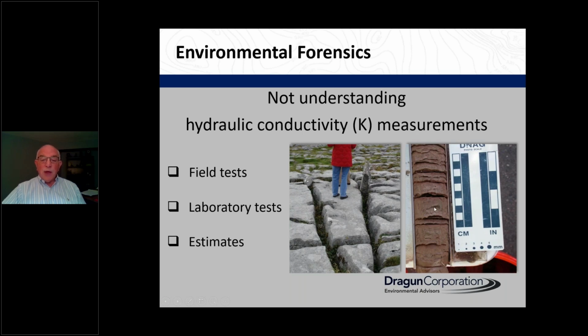And if you were to do a laboratory test like grain size distribution, you would lose this structure that is common in varved clays. So you need to know how the hydraulic conductivity was measured and whether it was appropriate for that purpose.